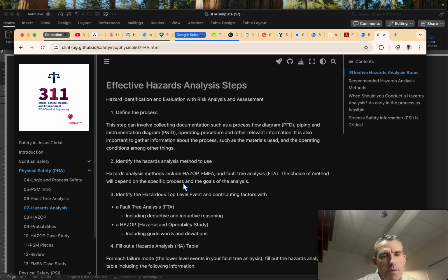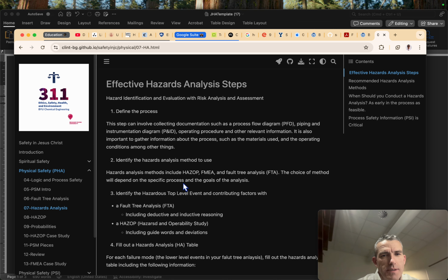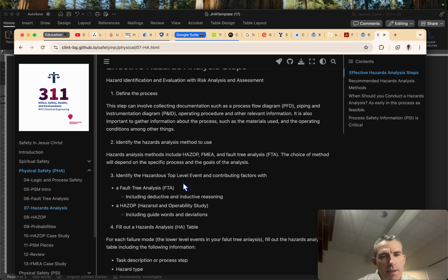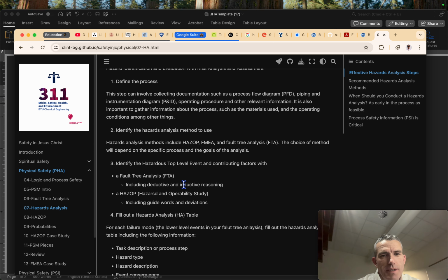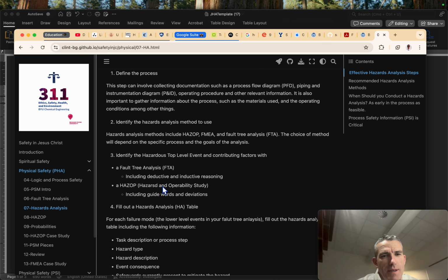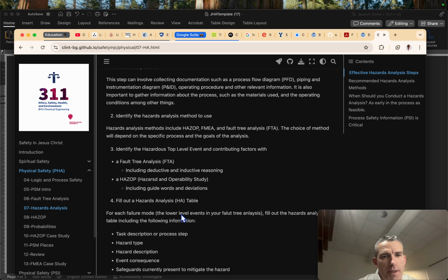Once you've defined that process and the scope of the analysis, you can choose a hazards analysis method. The methods that I used in the explosive, pyrotechnic, and propellant industry are fault tree coupled with a failure modes and effects analysis, or a HAZOP.